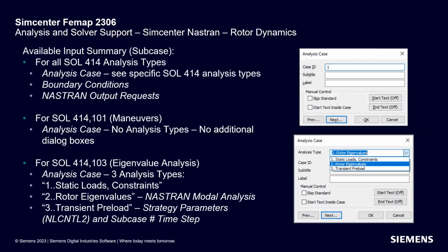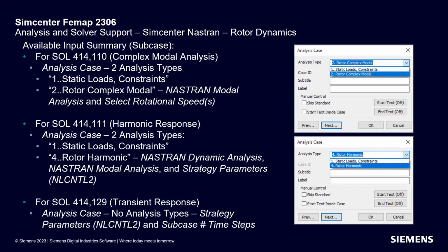So again, this is just a little bit more about certain analysis cases. You can only enter a case ID. In other cases, there's actually an analysis type that can be entered for each different subcase, and you can see, depending on if you're doing maneuvers or eigenvalue analysis, complex modal analysis, harmonic analysis, or transient response, you basically have some drop downs from the analysis type for your various subcases.